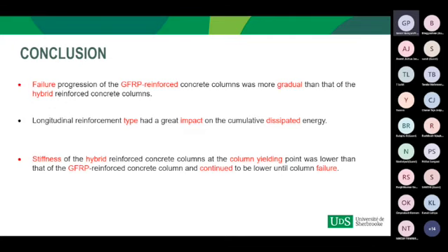And finally, the compressive behavior of the GFRP bar doesn't provide the elasticity required for the seismic response in high seismic zones, whereas steel bars in the hybrid reinforced concrete column give resilience to the column in the compression part and make it more suitable for high seismic zones.